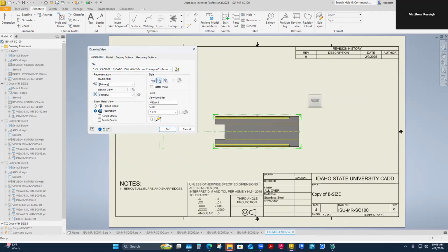Just as a side note, I can mix scales on here, but be careful doing that in CAD, or be careful with DXF files. Some equipment will scale all parts to the first part that has been placed on the DXF or cut file sheet. I think older machinery had a harder time working with mixed scales on the same sheet. I think it's not such an issue with newer equipment, but there is still legacy equipment that people use, and they're really careful about not mixing scales on cut file sheets.